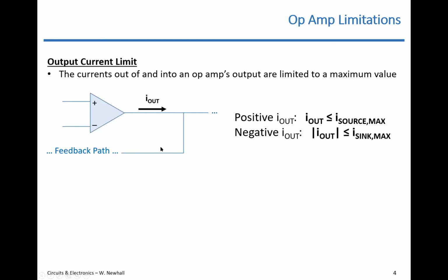Now, on the other end, you don't want those resistors too large for a couple of reasons. One, your amplifier gets noisy. We're not going to derive that, but I'll mention that. And also the negative feedback assumption that VID goes to 0 actually starts falling apart if you use very large resistors.